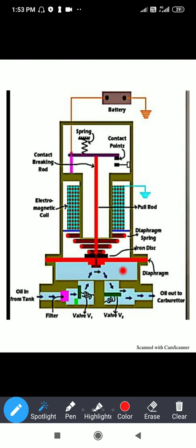of pump is that without starting an engine, the fuel can be supplied to the engine. Okay, there is no need for the start of an engine because it is directly connected to the battery. With the help of the battery, continuous power is supplied to the solenoid, by which the fuel is started. Okay, there is no need to ignite the circuit so that the pump can be started. This is the major advantage of this pump.